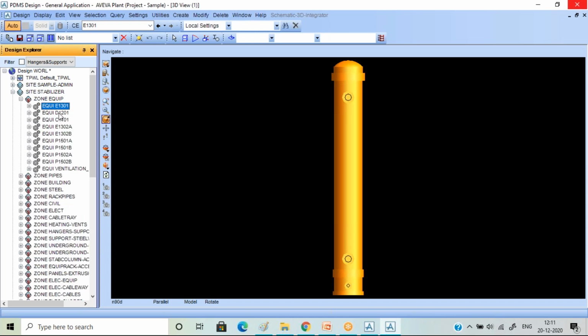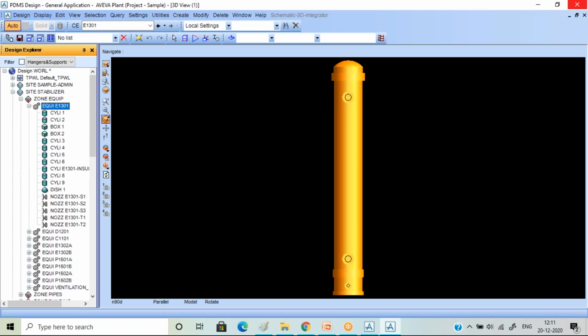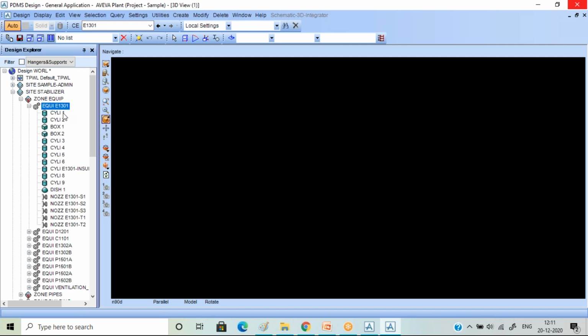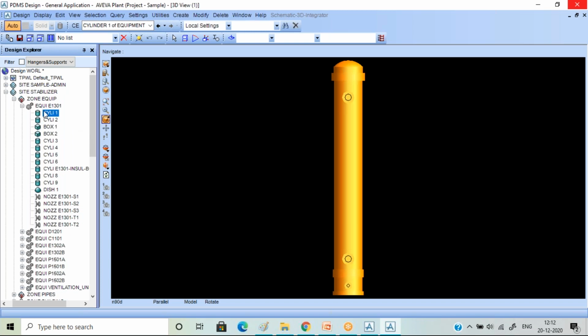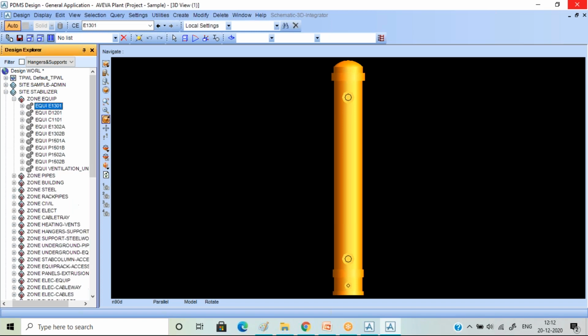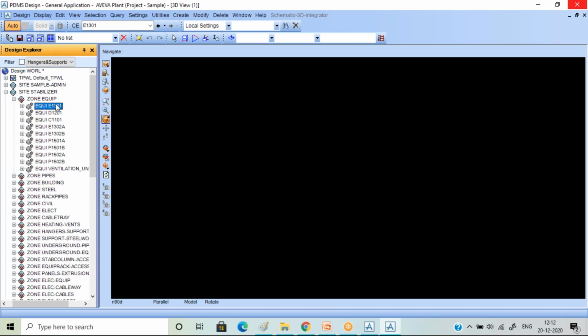Okay, next we move on to your column. This was what I was basically explaining in this entire section. If you click on remove current element from the draw list, it will remove my complete equipment. Say I want my particular sections to come in, like this particular thing, I clicked onto it, and this complete equipment is coming into play. Now I only want the nozzle section or a particular part of the equipment, so that again I can model it into a sub equipment, and my hierarchy has to be 100% correct.